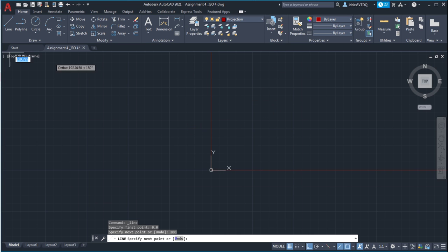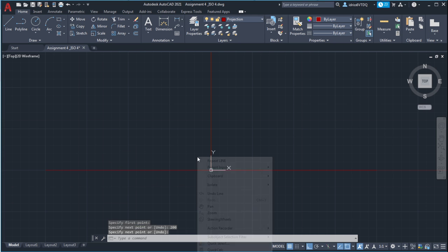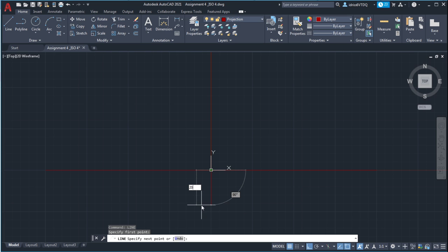All right. The line 100, 200, line 100. Okay, because this is third angle projection, the 45-degree line is supposed to be, sorry, not in the middle, should be in the first quadrant. First quadrant should be